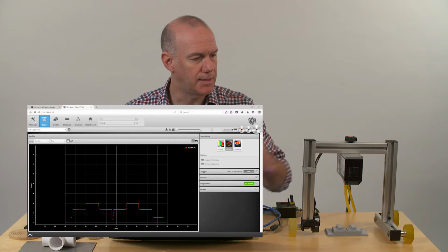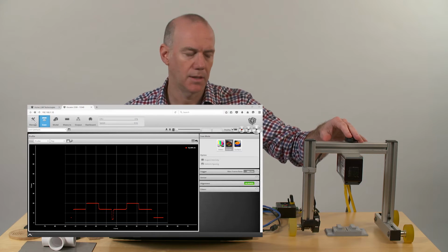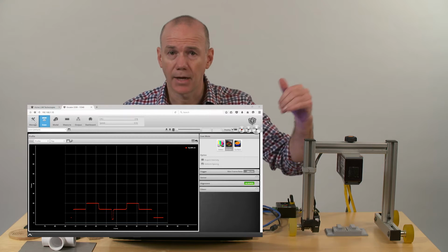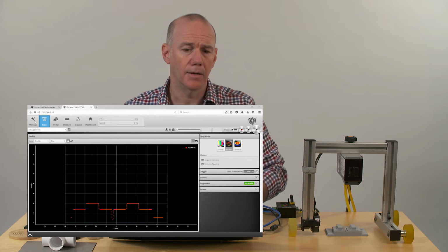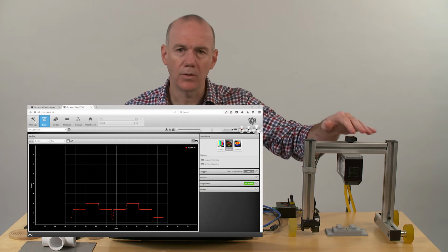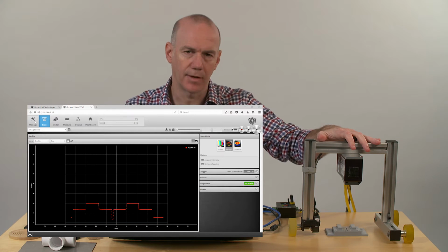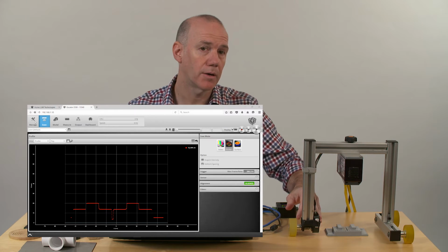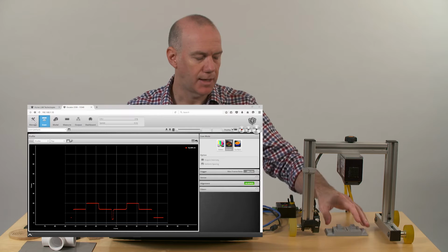So to do that, I need to induce some form of motion, whether there are conveyors going by, or you have this on a linear slide or a robot arm. You scan over an object, and that's how you build a map. This rolling gantry that we have for demonstration purposes has wheels on it. It's got an encoder on here that I can activate and scan objects.